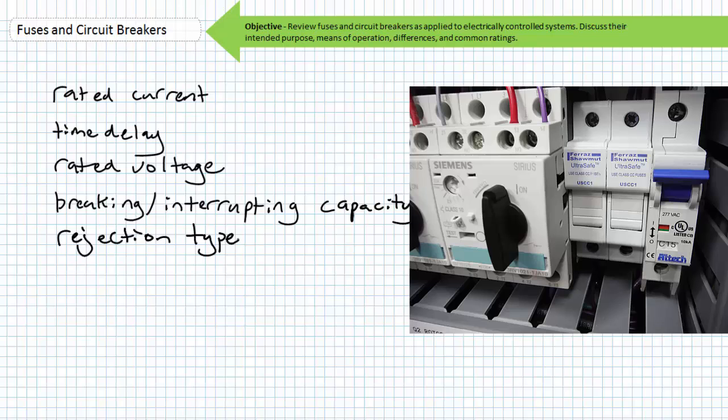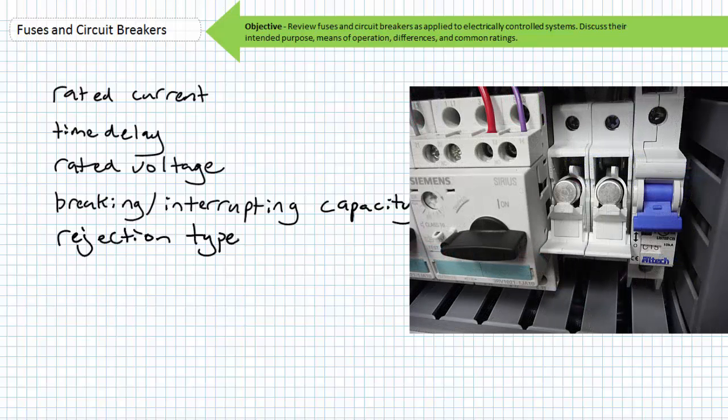Once the system is properly shut down and properly locked and tagged out, only then can the fuse holder be opened and the fuses inspected and/or replaced. In addition to following proper lockout and tagout procedures, keeping the fuses with you while you perform a maintenance procedure establishes yet another layer of protection, preventing the inadvertent startup of equipment.